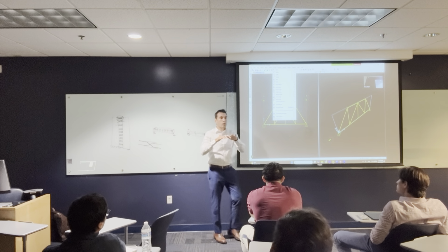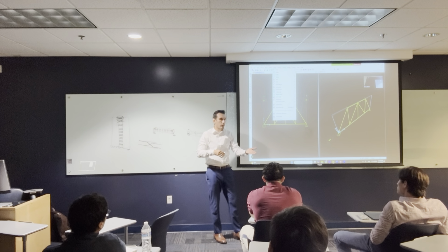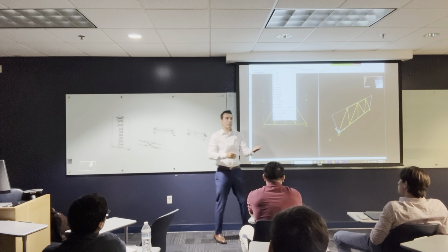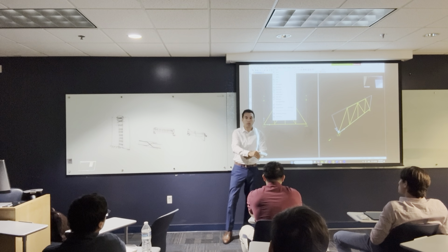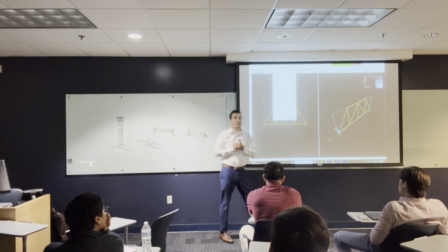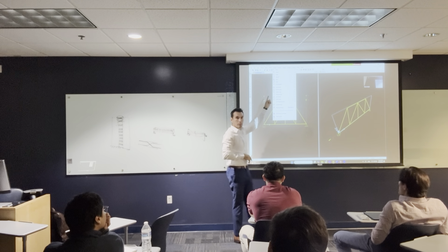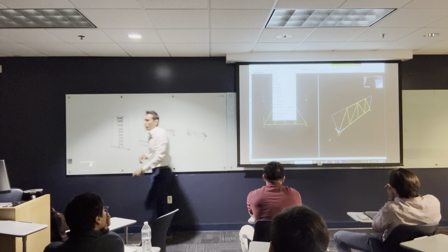At first, when we defined the frames and I drew the frame, I told you if you didn't define the frames, SAP 2000 is going to assign its own frame, right? But let's say down the road you wanted to change the frame section. We made this frame section concrete. Let's say you want to make them steel. You can select them and assign a new frame or assign a new shell. So you can do that.